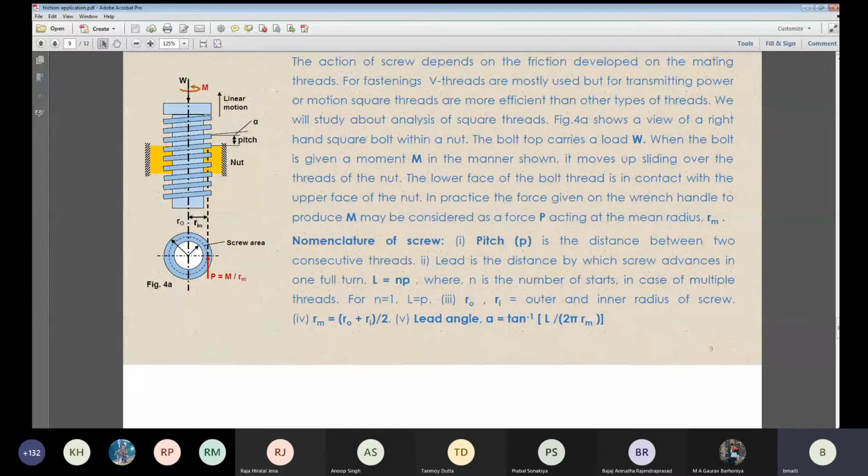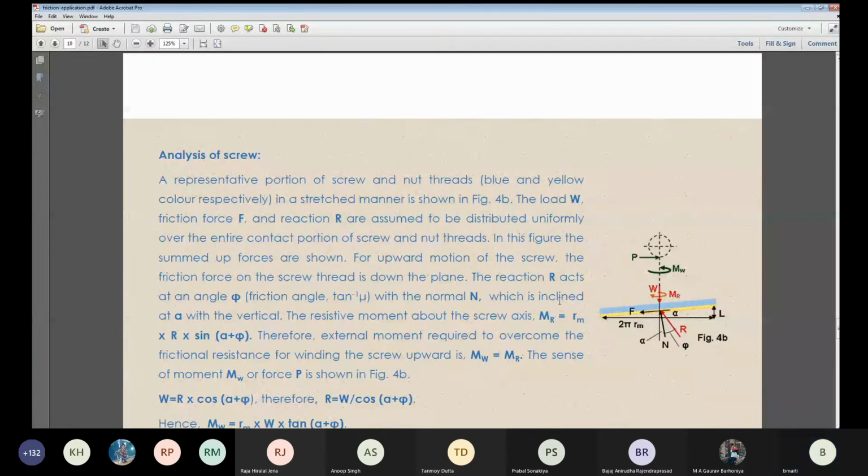One winding of one thread. Just forget about L, forget about one single pitch. This is the last time I'm talking about it. The blue one is the thread. You wind a thread by one rotation. By one rotation, how much have you moved up? 1 mm, the pitch is 1 mm. Now that thread, you cut it off and stretch it as a straight line. That straight line is the blue straight line, the thread which was wound onto the body.